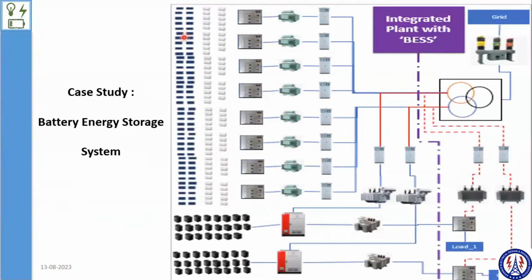See, we have calculated the solar side, the inverters, and the ACDBs. We have done this transformer and this individual VCB part. Now we are clubbing it to your main existing, or I can say the upgraded, transformer. We are just tapping into this, right? This transformer has a capacity of, let's say, 50 megawatt, with 33 kV on this side and 132 kV on this side.